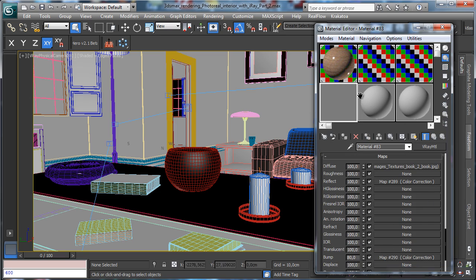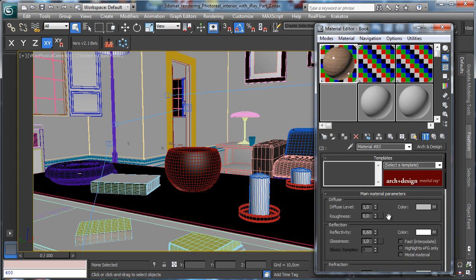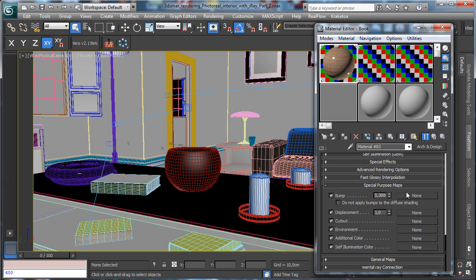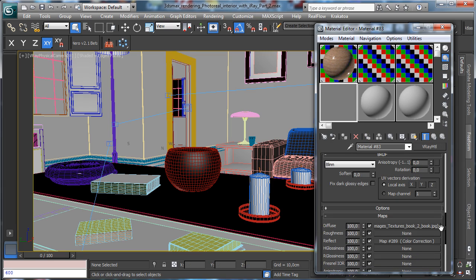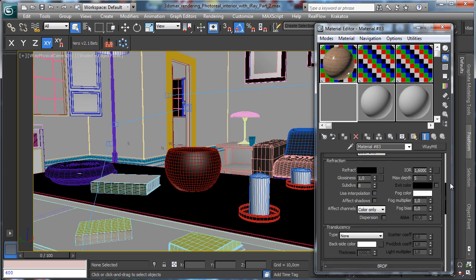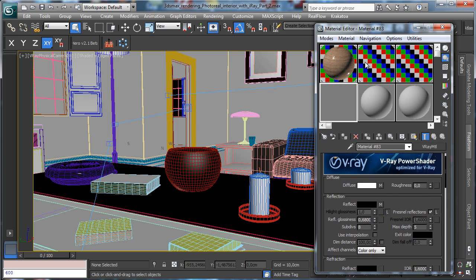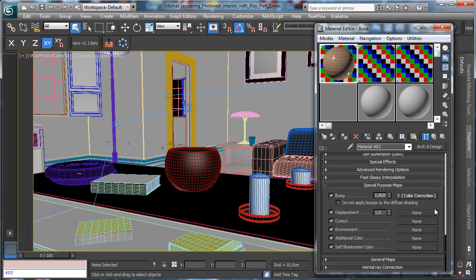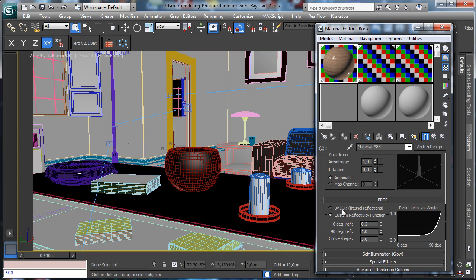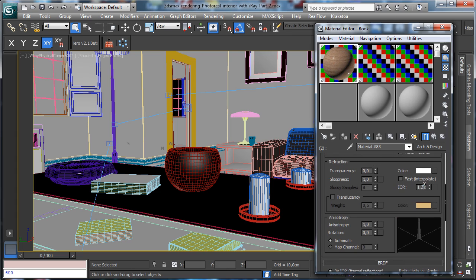And then we have the bump, and let's set 0.8. We have to check the general parameters for the material. We have 1.6 for the iRay, so let's do the same there. We say use the iRay, and we set it to 1.6.